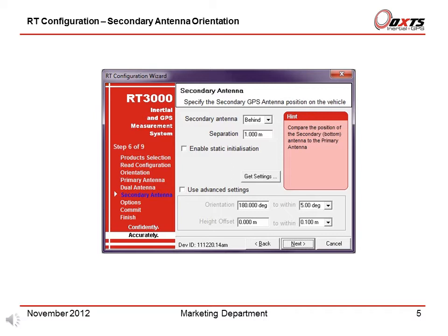In reality, the multipath reflections from the window screen will degrade the performance of the system. Getting the angle wrong by more than 3 degrees can lead the RT to lock onto the wrong heading solution. The performance will degrade or be erratic if this happens. The RT does not estimate the distance between the two antennas. It is essential to get this right yourself, otherwise the system will not work correctly and the performance will be erratic.